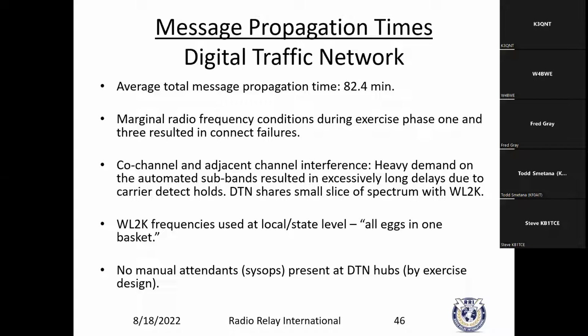Whereas the radio telegraph operators, some of whom had beams and things of this nature and amplifiers, could go ahead and target the disaster. You turn your TH6DXX, or your tri-band beam, or your log periodic toward Washington State and/or Alaska, and you've got yourself a much better circuit, right? You might have a 5-6 dB difference. That flexibility that manual methodologies have to dynamically respond to propagation conditions proved to be a big advantage for CW.